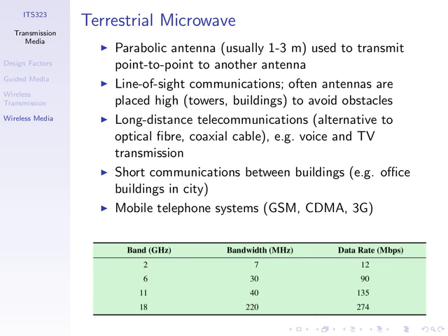That's why for some applications the antennas are in fact placed on top of high towers, so buildings, trees and so on are below the signal. The best example is the connection from our other building to our Rangsit campus. We have an antenna on top of the other building at this campus and one at Rangsit campus, and those antennas are aligned to point at each other, and they are a point-to-point terrestrial microwave application. No significant building between the two.